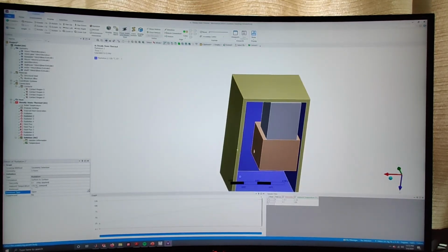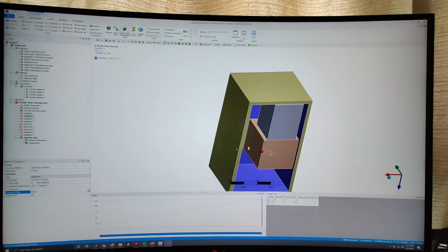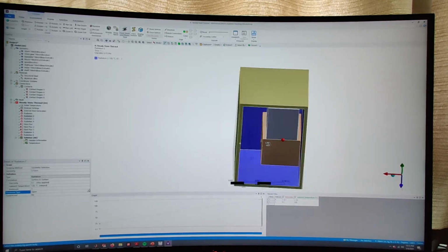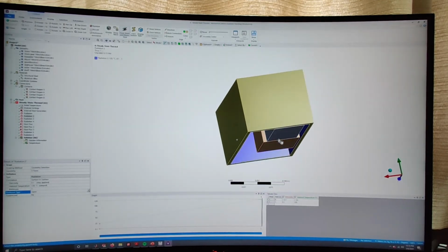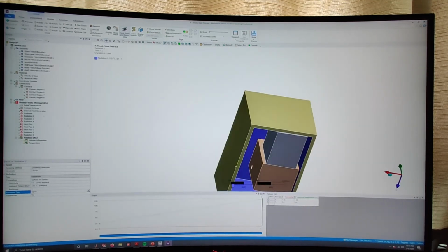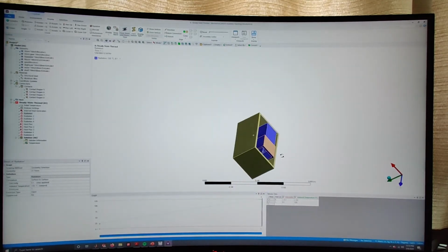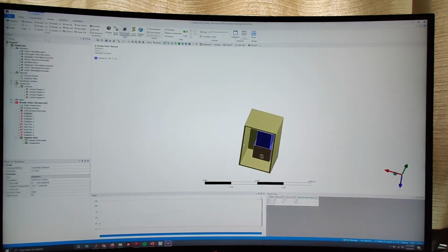So instead, I just have this ambient temperature, so whenever it runs into an error, it just radiates to an ambient temperature of 120 C. That's higher than anything I expect to see, so it's not going to be an issue. It'll be conservative. So here I've selected the inside of this doghouse, and then with this radiation 1, it's all of these faces that I expect to radiate out to those other faces.